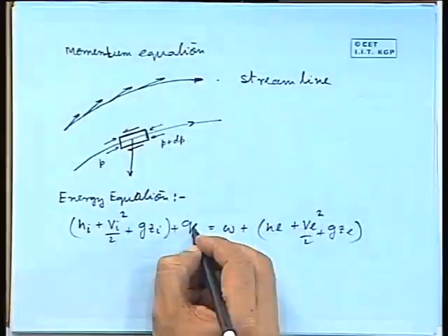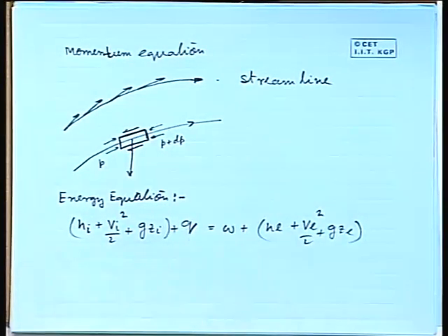But when we are discussing fluid flow, in most fluid flow we will find a number of situations where there is no exchange of thermal energy. And we will also find situations where there is no mechanical work done. In those cases, the generalized form of the energy equation is applicable, but we can get a simpler form of the energy equation. That simpler form, which we get in a large number of fluid flow situations, is known as the Bernoulli equation.